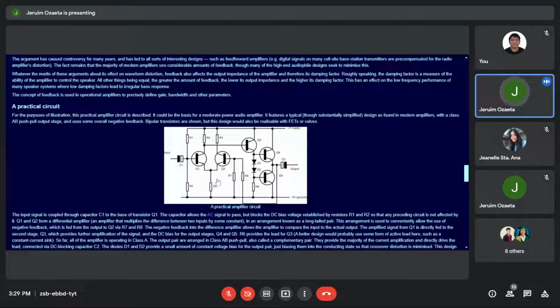So R4 and R5 serve as a voltage divider when Q2 is conducting through the bias at the base at R sub 7 and R sub 8. Okay, R sub 8 must be coming from some other source in order to influence the bias at the base of the Q sub 2. Anyway, this Q sub 2 appears to be a stabilizer of the input signal.